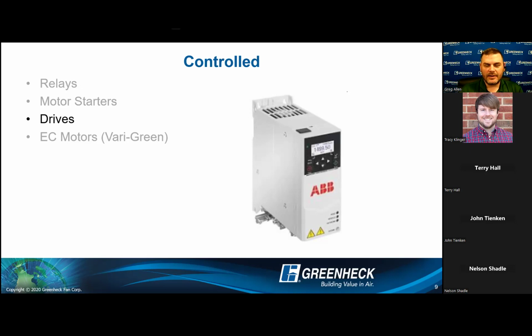Now, most drives, and I'm going to say most because I don't know every drive out there, right? But a lot of the drives I deal with, you can tell it to accept a dry contact closure for an enable or start, right? Or you can tell it to a different terminal to accept a voltage input. That's a start stop.